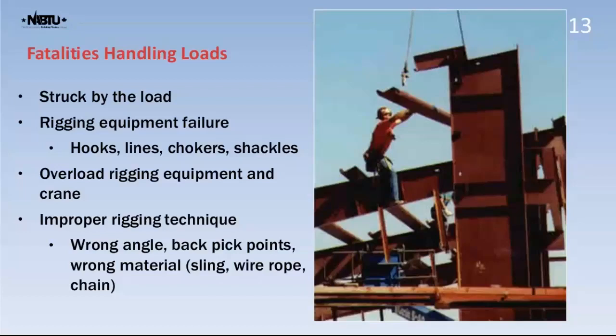I had a case of a whole pallet full of 5-gallon buckets of paint that were picked up by inadequate pick points, and as it was being moved by the crane over the deck of a ship where it was going to be placed, the pick points where the rigging connected to the pallets broke, and well over 100 gallons of paint broke open when those cans hit the deck. So fortunately nobody was underneath it, but all kinds of things can go wrong with the rigging.